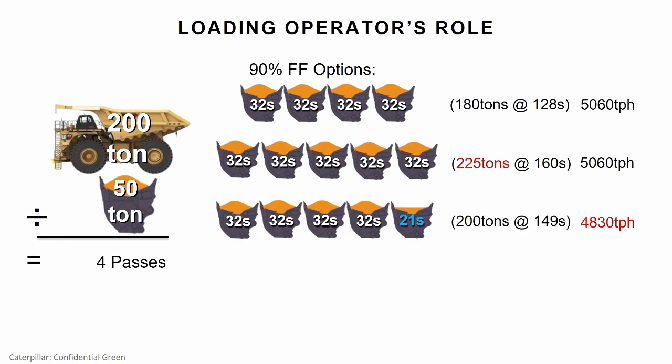The other one we see often: you put a 4th pass on there, you see 180 tons on the scoreboard, and you decide it needs a little light top-off pass, right? If you're doing that, you may think it's fast because you're not spending a lot of time in the bank, but you can't reduce the swing time of your pass. So you're just wasting time overall. You're getting your payload, but you're taking it with the trade-off of your cycle time. So you're hurting your productivity.